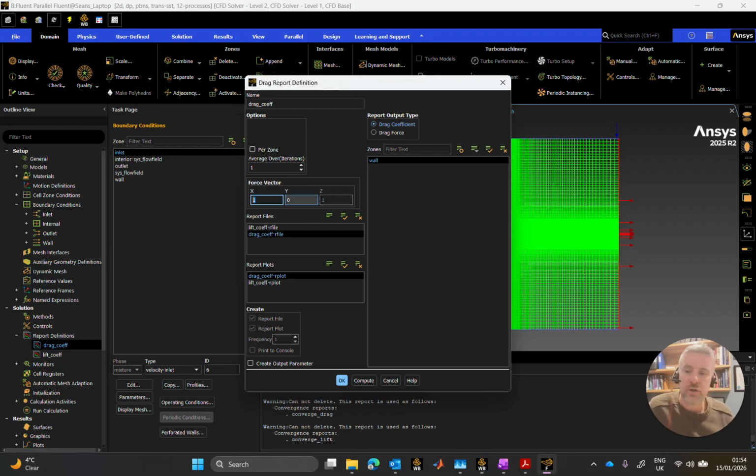At the minute, I cannot change it with the named expression that I just wrote, which just completely takes away any sort of advantage of writing that. If I have to come in and type this in as 0.8 or whatever, and whatever the other one might be, 0.35 or something, I may as well just go into the velocity and do it there as well. I'm trying to set up a case here where I don't have to come into it, right? So that's why I want to delete them out.